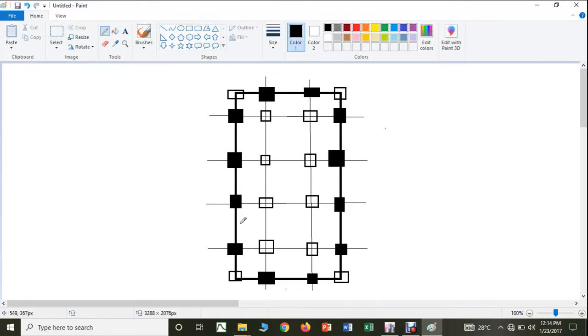But the moment developed here will not be nullified by any beam, because you don't have any beam here. Therefore, it will have axial load and one moment. So these columns which are made in black color, we always design them as uniaxially loaded columns. That means one axial load and one moment.